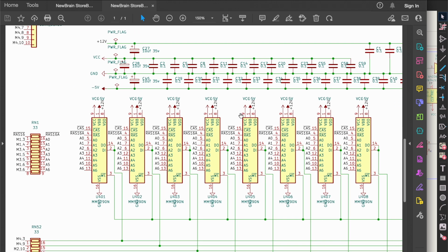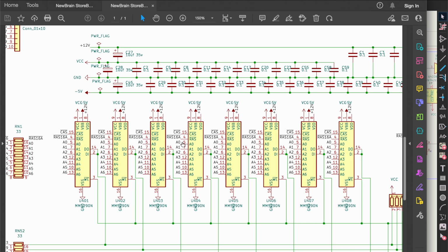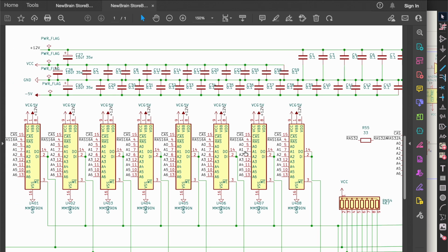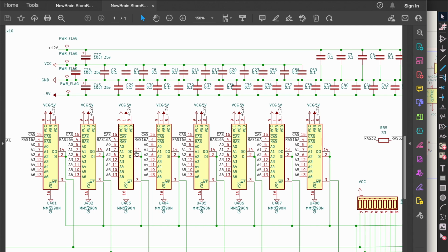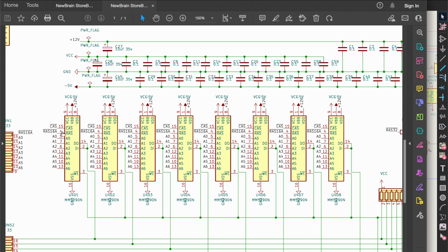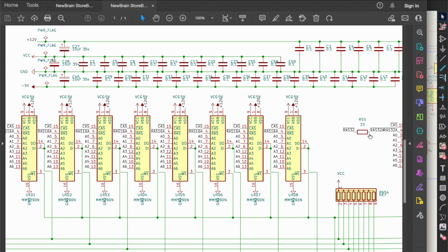Well, the existing board at the moment gives 32K internally. This is via two 16K banks. We've got a 16K bank here and a 16K bank there. These are 16K by 1 bit, so we've got 8 of them, which makes 16 kilobytes. Because they're DRAM, we've got 7 address bits here. The addresses are multiplexed: a row address and then a column address. Because we've got 2 banks, we've got a RAS16 and a RAS32 signal.